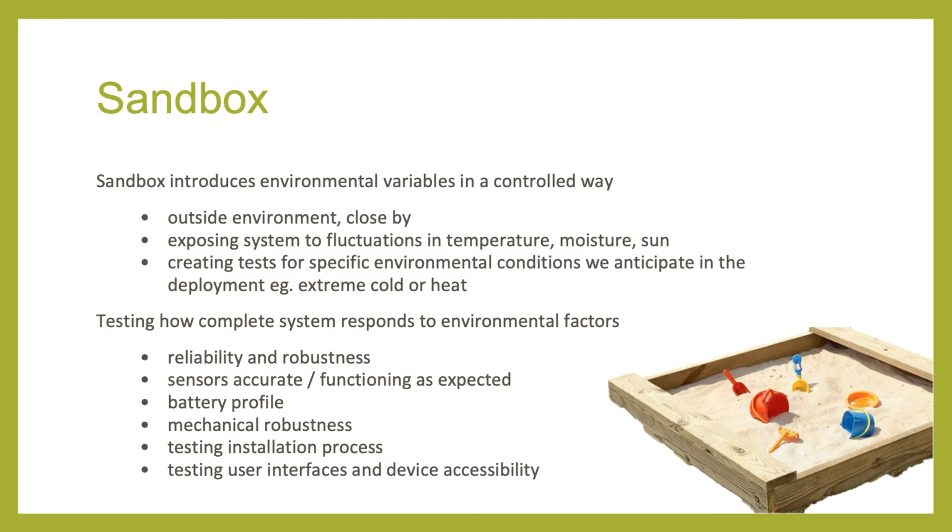Once we've tested in the lab, we take the device and put it outside in the sandbox. Then we run the same accelerated testing. The sandbox is an outdoor environment where we start to introduce environmental conditions in a controlled way. Again, it doesn't have to be fancy, your backyard or a park if you have access and permission. But you want it to be close by. If a device fails in the sandbox, you want to bring it back into the lab, so you don't want to be traveling too far between the two.